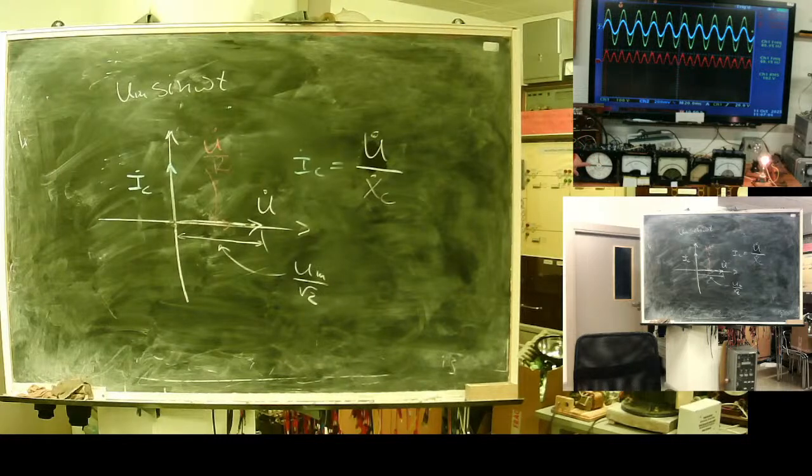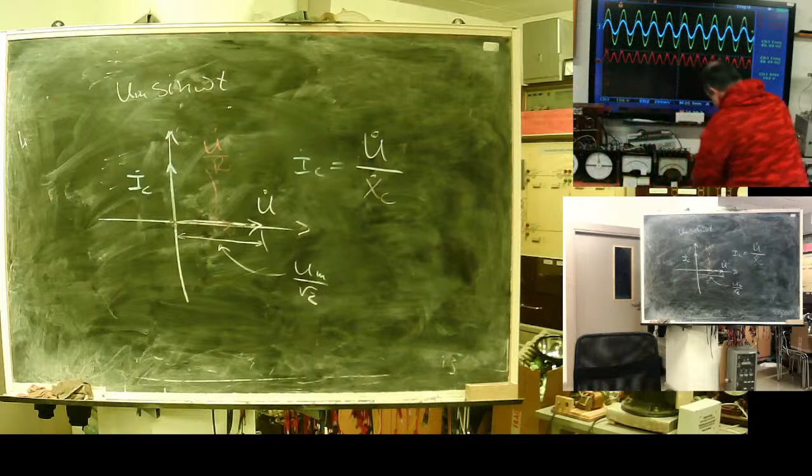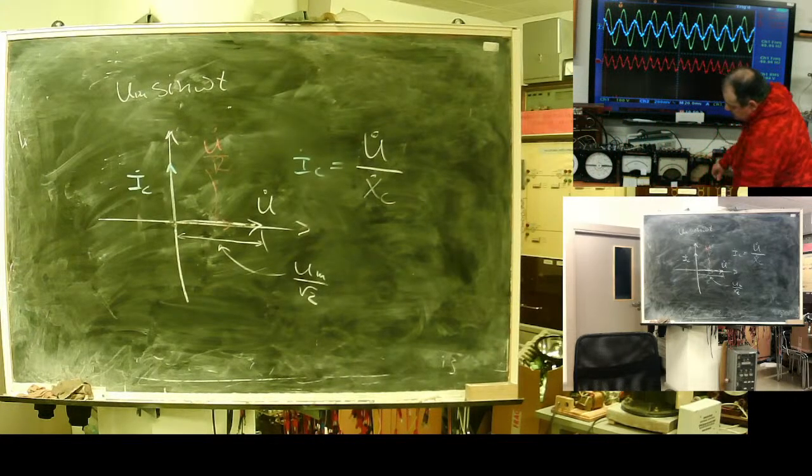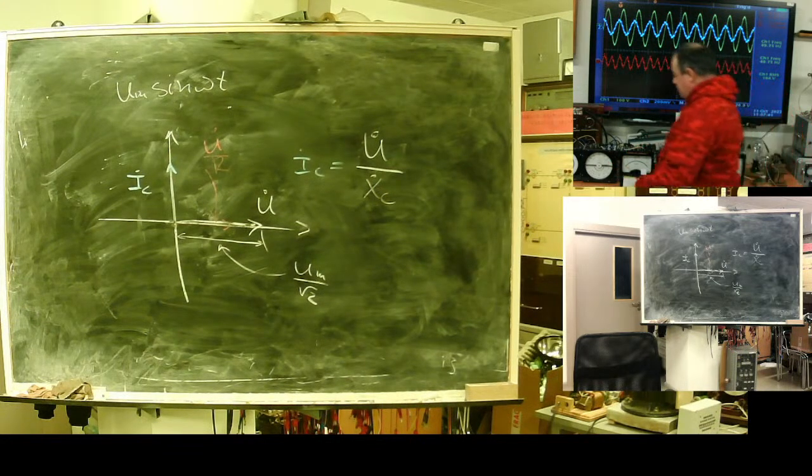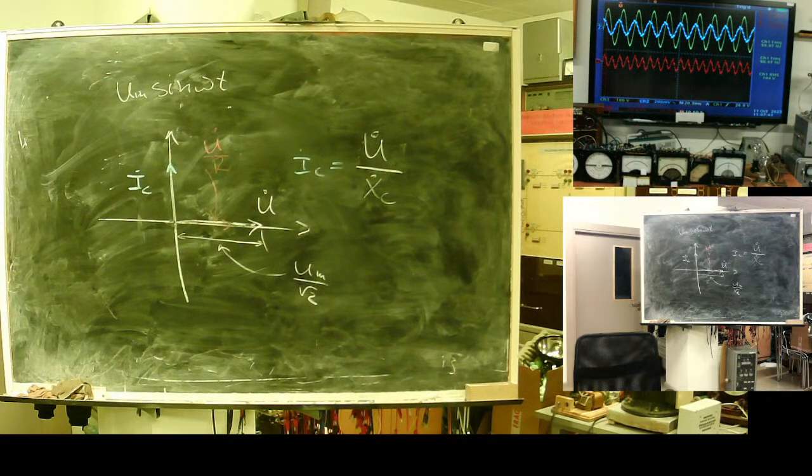It shows power factor, which is the cosine of the angle between current and voltage. The numbers are the value of the cosine, but the needle shows us the angle. The only problem is it has a 0 here, vertical. It should be like this. But watch, I'm adding a capacitor. See where it goes? Yes. Lead. It's a leading power factor.